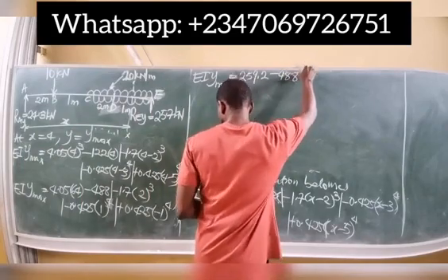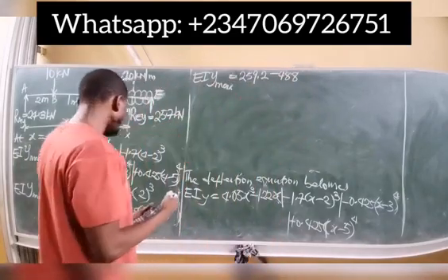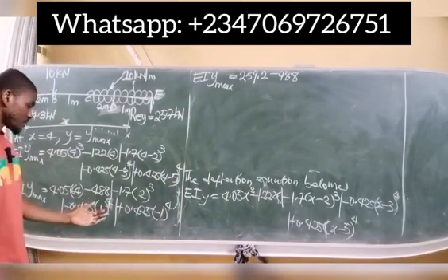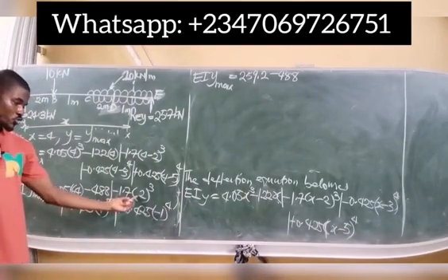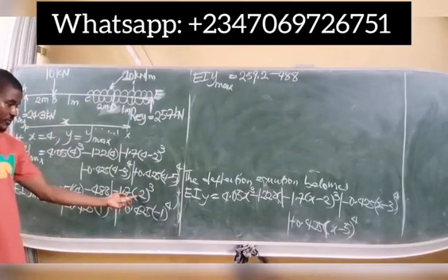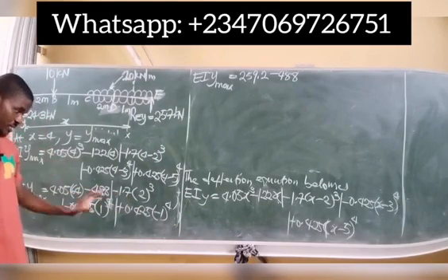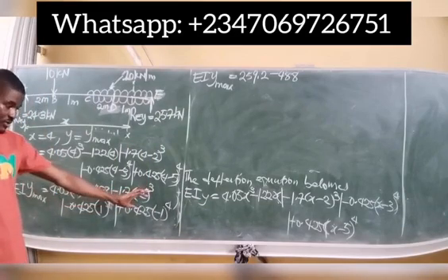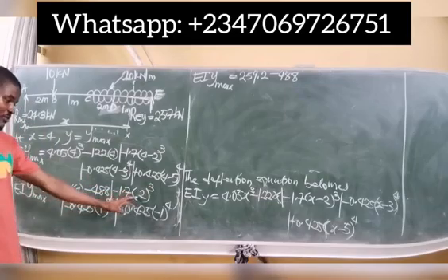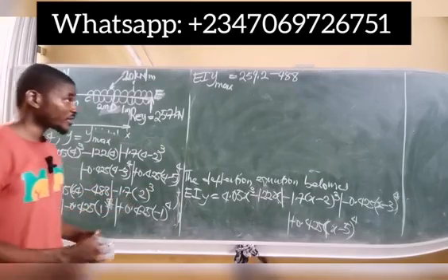Put down your Macaulay's bracket. So let's examine the Macaulay's bracket now. I have plus 2 in the bracket, so it's positive, which means I can work with this Macaulay's bracket. It's not negative, and the value there is not less than 1, so you can eliminate the bracket.